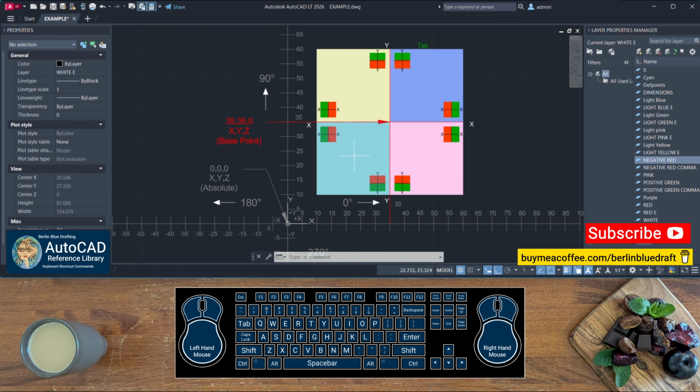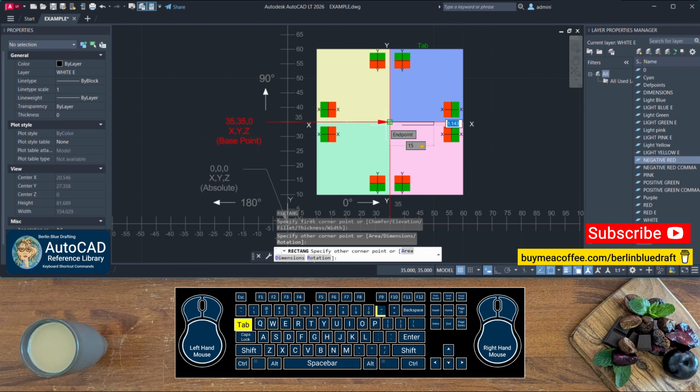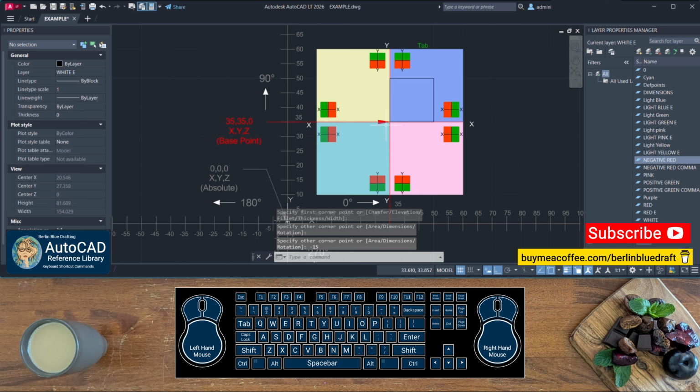Type REC to bring up the rectangle tool and enter. Click onto the first base point, 35, 35, and enter. Type -15, tab, type -15 and enter. The box is now in the blue quadrant.